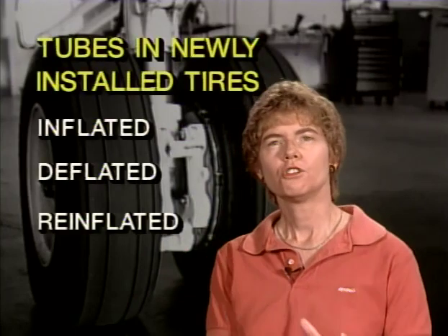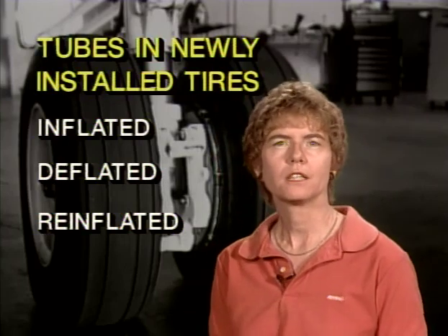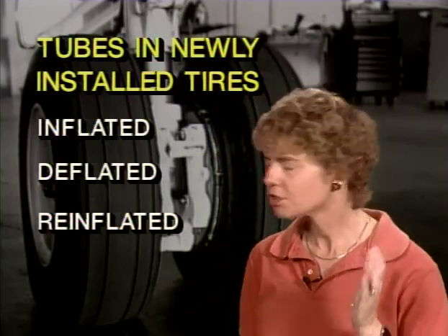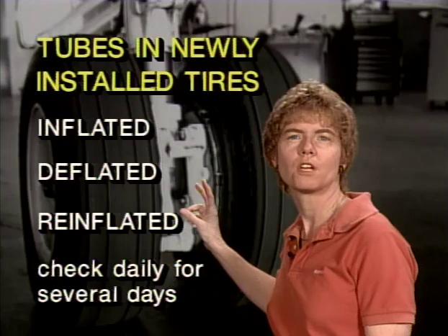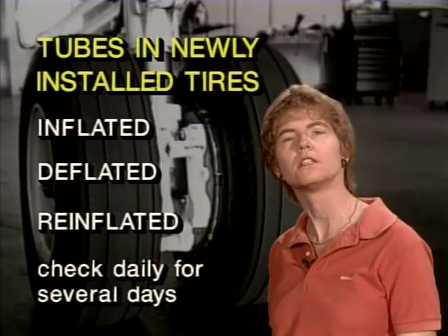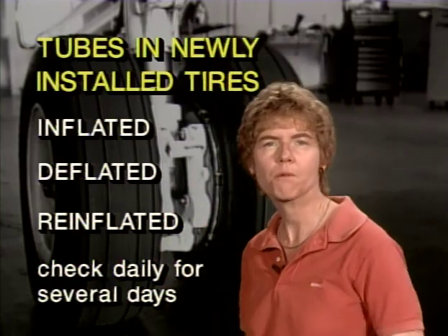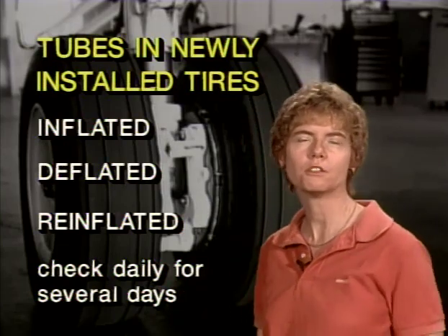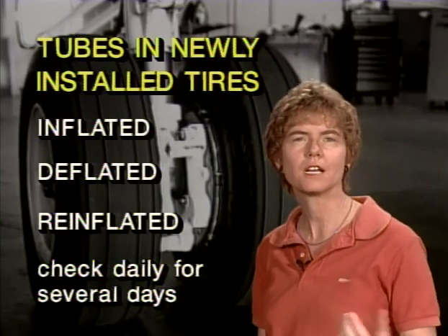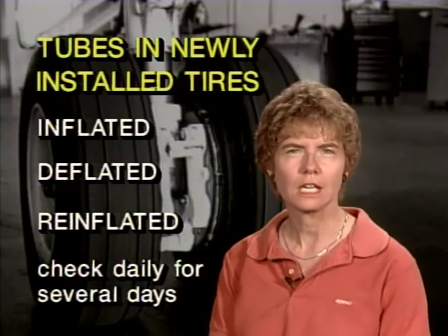Now, let's assume that you're installing tires with tubes. Tubes in newly installed tires, you first want to inflate them, then fully deflate them and reinflate them to the correct pressure. And the reason you do that is to make sure that the tube is going to position itself correctly inside the tire. Inflate it, deflate it, and reinflate it, and then check it for proper inflation daily for several days. A newly mounted tire with or without a tube, you should check it for proper inflation daily for several days just to make sure that it's seated properly and that it's not leaking on you.